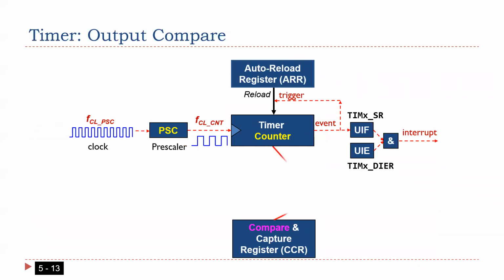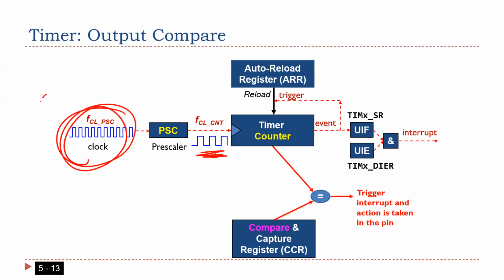Okay, guys. Here I'm just explaining, as you see, we have a counter. This counter has a clock, as you see here, the input clock. As I'm going to explain later, this clock is actually generated from the system clock, which is around 2.08 or 2.09, something like that, megahertz.